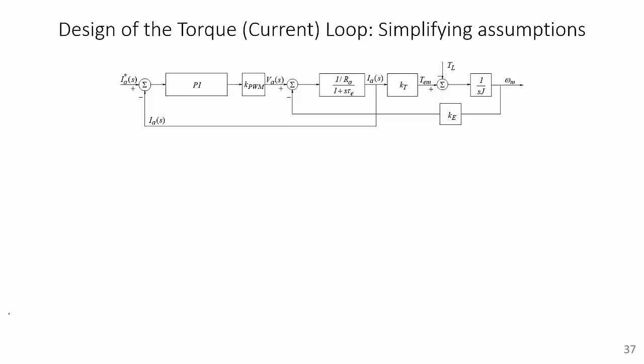So let's go ahead and design a current controller to control the armature current of a DC motor. This section is the motor model that we have already modeled using Workbench. We have the 1/(SL+R) transfer function that converts the difference in the terminal voltage and the back EMF to current. Then you scale the current to get the electromagnetic torque, and you integrate the differential torque by 1/(Sj). You would get the speed, and the speed you scale by the back EMF constant, you'll get the back EMF, and that will close the loop. So this part is already known.